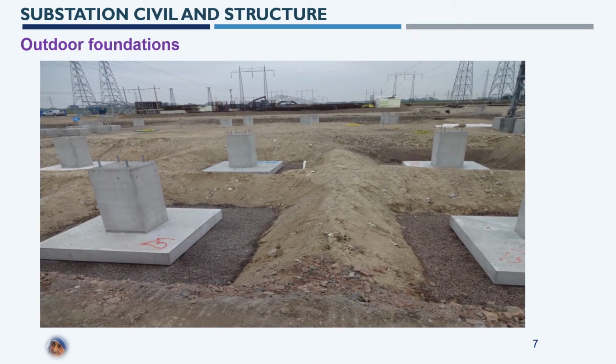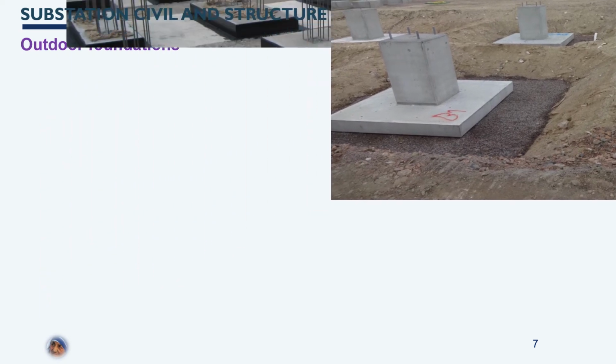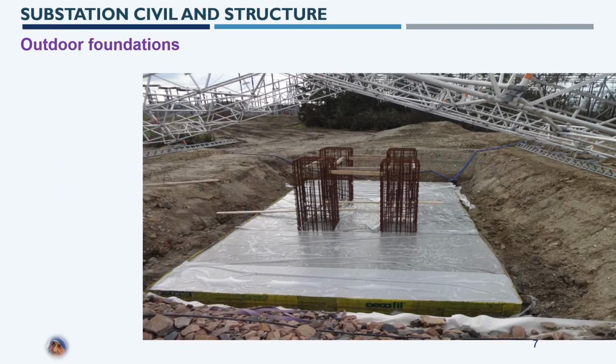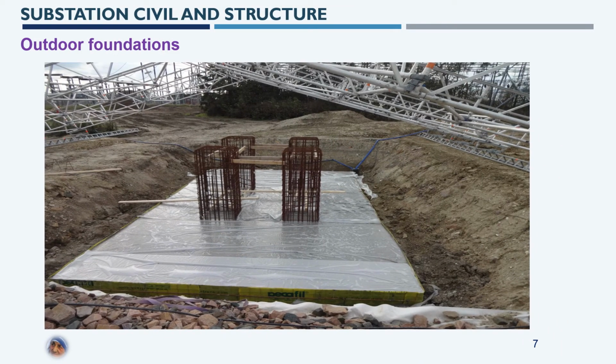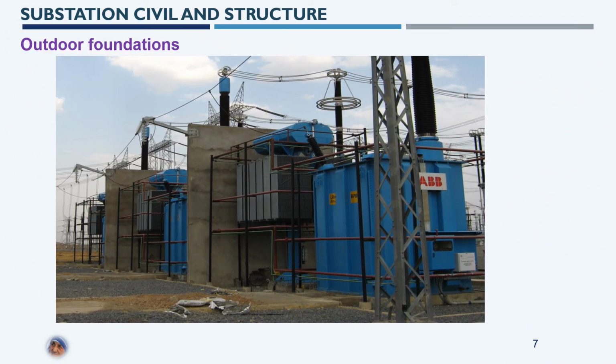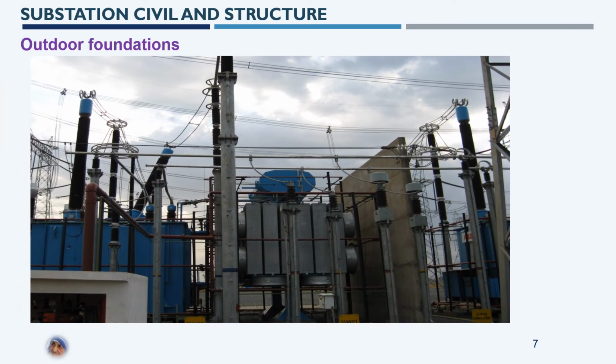So this photo shows a precast single isolated foundation which is ready for the structure to be mounted. And this picture shows a single and combined foundation for two columns which are prepared for a building. This is a tower foundation having 4 pedestals over it, which shall be called a mat or raft foundation. This is a transformer foundation along with the firewall and transformers. This is a rear view of the transformer with the tertiary equipment and its support.